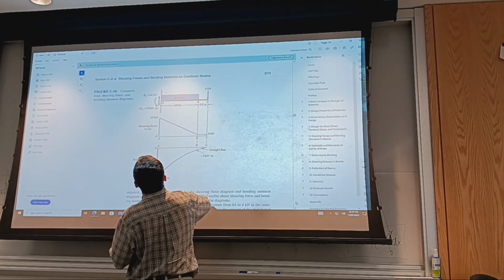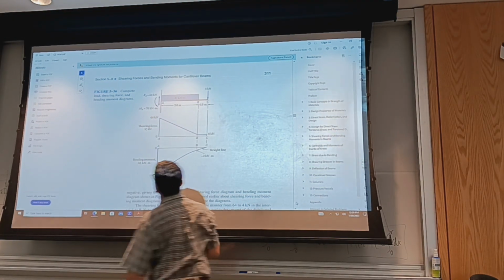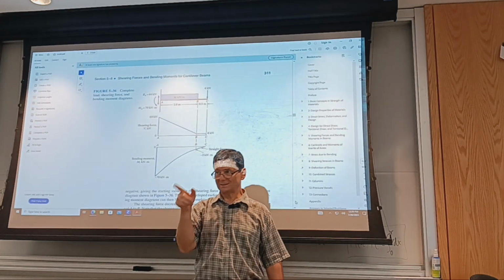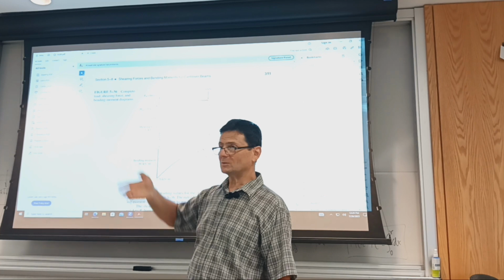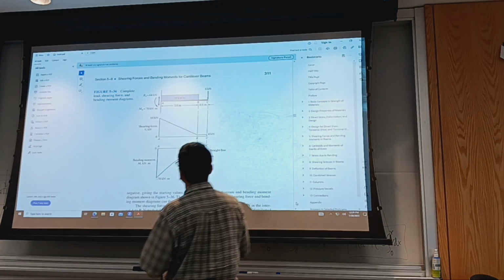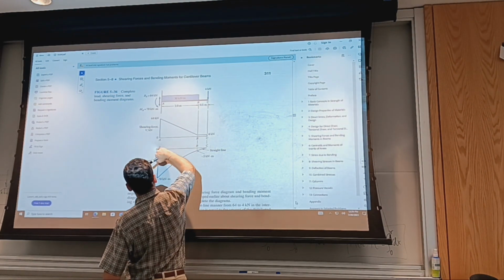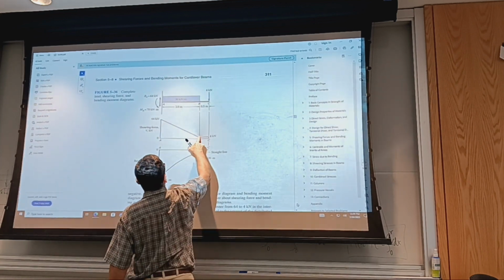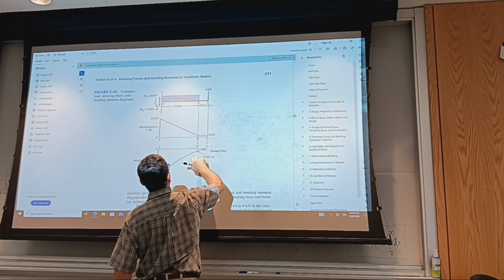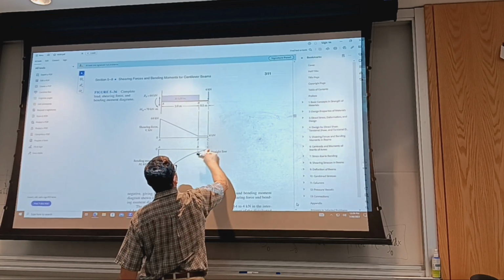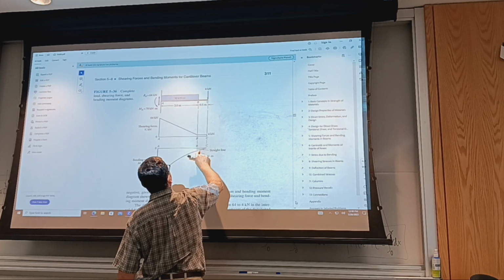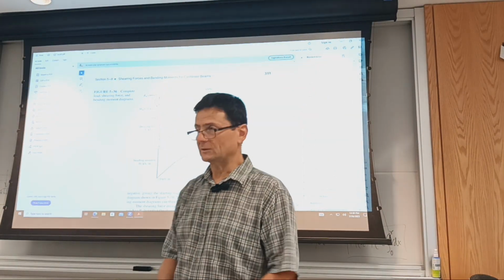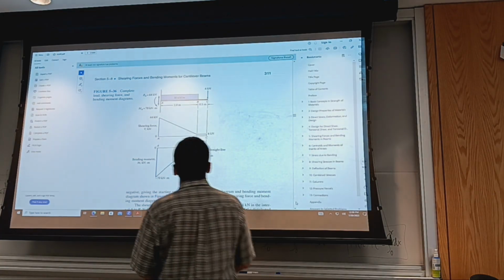Okay, and then you have the moment, and it starts with this moment, which is negative. That's why you begin with a negative value. Remember, an external moment that is counterclockwise causes the diagram to drop by that amount. Of course, I go from 0, I drop this amount, and then this was linear. This would be a second order curve, and then here it continues like a straight line with the same value left and right, because I don't have any external moment applied to the beam. Okay,